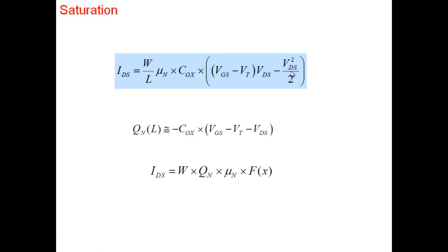But at the drain side, the charge is actually decreasing. If charge is decreasing, then this term has to rapidly increase to compensate not only for the decreasing charge, but also to allow the current to increase. So the field next to the drain builds up very rapidly, to high values. But this term has an upper limit.